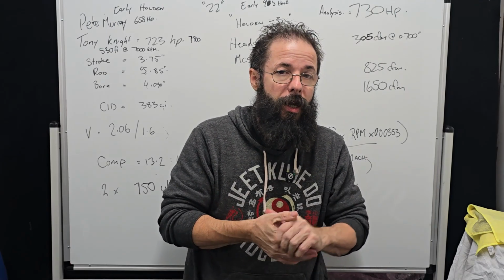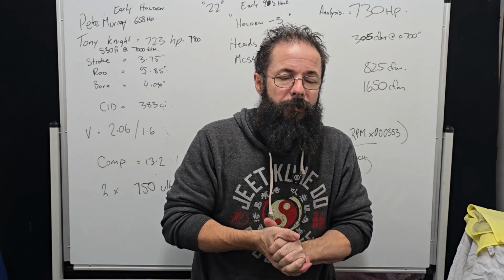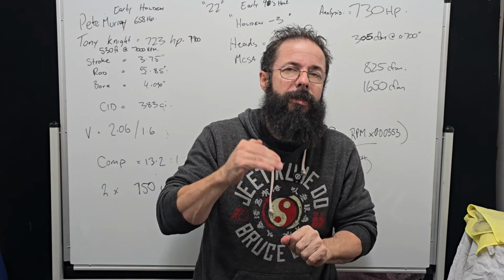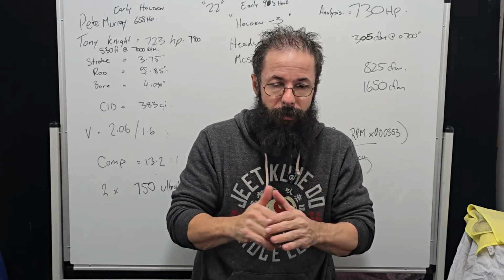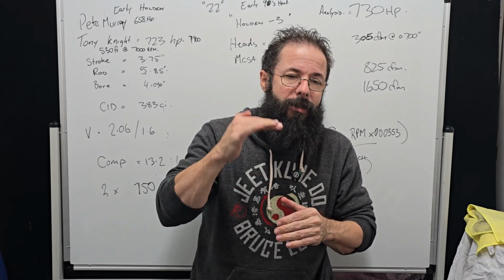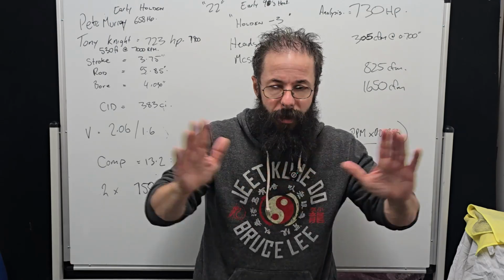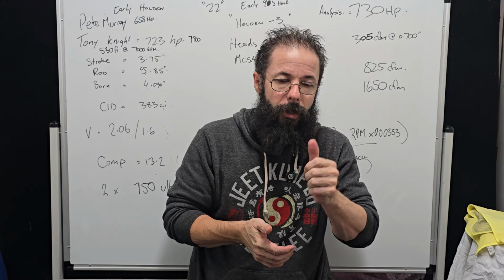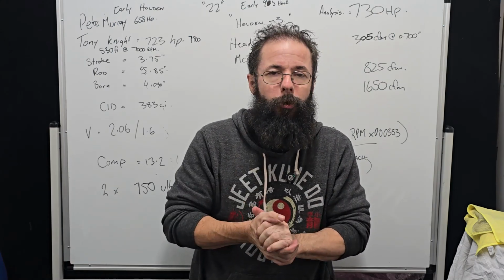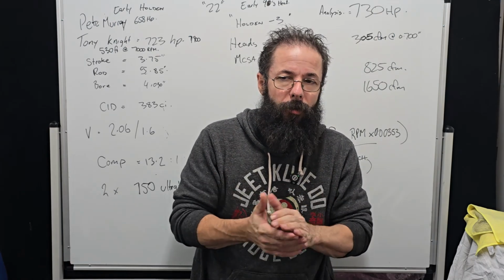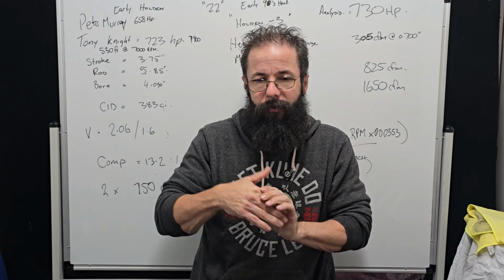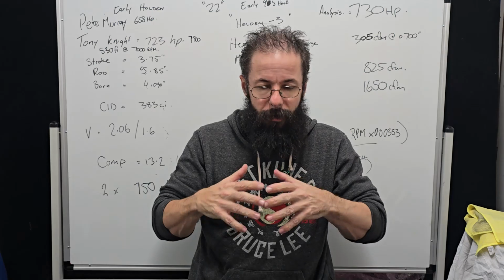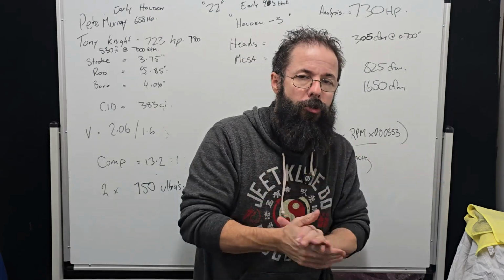We'll go through and actually calculate this combo just to show you it's not too bad. And again, this is max effort carburetor, so this would be the maximum size carby you'd ever want when using my application. So again, you can choose lower values, but you have to be realistic with it. So we have right up until pro stock. So obviously you don't want to select the pro stock carburetor efficiency for a street car.